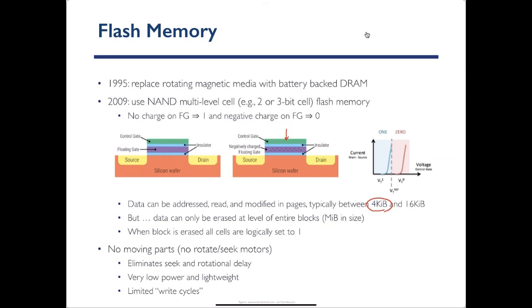The voltage that you supply to erase a cell is high, and it kind of distorts the cell. If you keep doing it to a cell, after a while it doesn't respond anymore. The Flash cells are dead after a while.